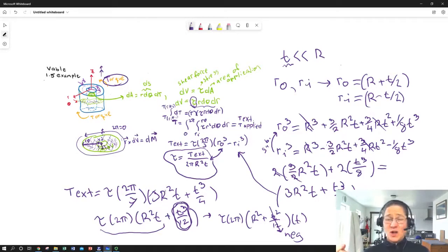So if someone says this is a thin-walled cylinder, you can use that much easier and simpler expression relating torque on the cylinder to the shear stress at a cross-sectional plane across it. And in fact, that very configuration with the thin-walled assumption forms the basis of an adhesive shear stress test fixture. It's actually a standard test fixture. Use a very small thin-walled cylinder that you glue together very precisely so the ends match up, and then you twist it, and you relate measured torque to the time that you begin to see some deflection or failure. And you would use this formula using R and T from your test fixture to calculate your shear stress for that adhesive, and then you can determine how strong your adhesive is in shear, which is how many adhesives work. They're usually loaded in shear.